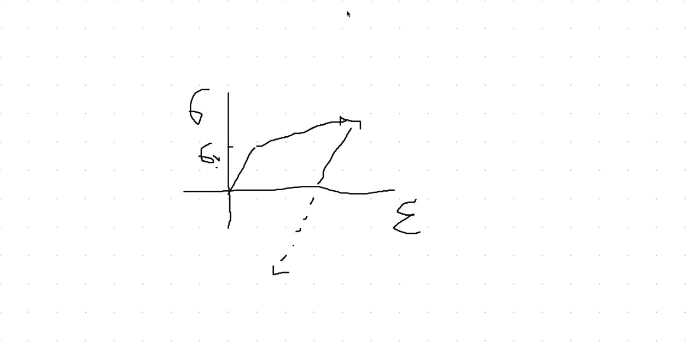There's something called the Bauschinger effect. And then yielding starts much sooner. So it starts already here. Obviously, this value is not the same as that, but something did happen. So basically, people introduced something called kinematic hardening. They said, okay, the origin of the elastic domain has been moved. And then you can start yielding at the same distance, from this origin to the top. And then you can produce much better hysteresis loops as you go along.